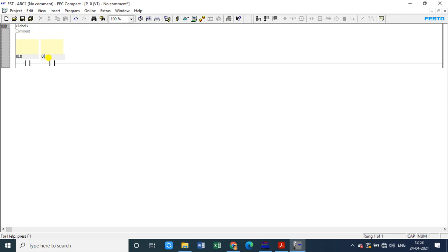So B minus is nothing but the 2S1 limit switch, which will get pressed at the end of the cycle or of the process. So here that will be 2S1. 2S1 means 1S1 is 1, 1S2 is 2, 2S1 is 3. So it's I0.3.